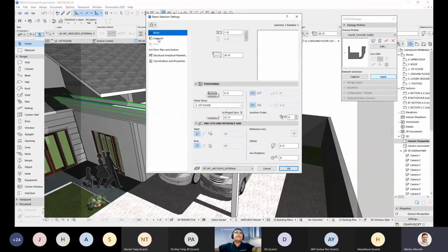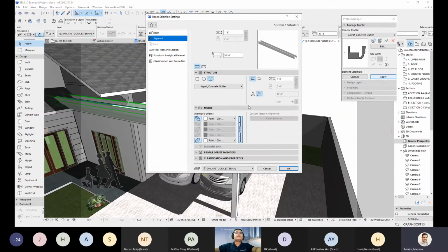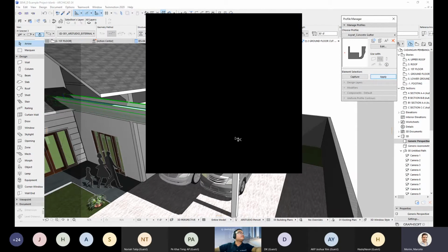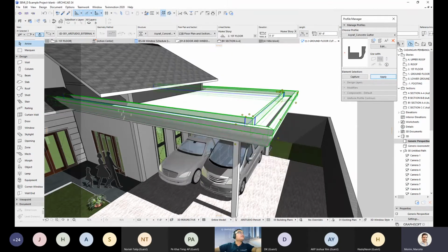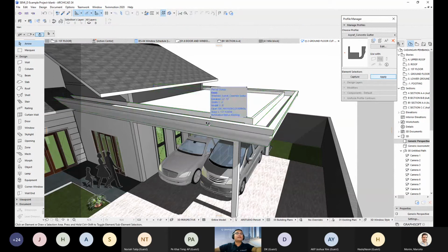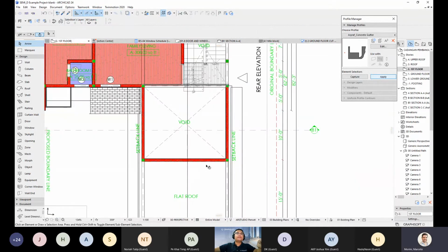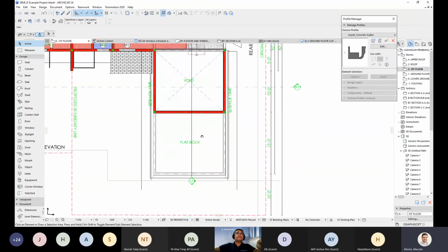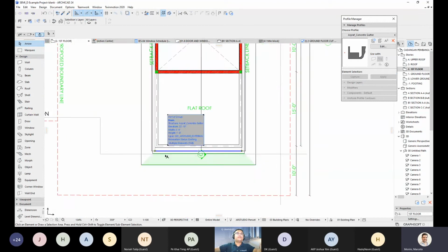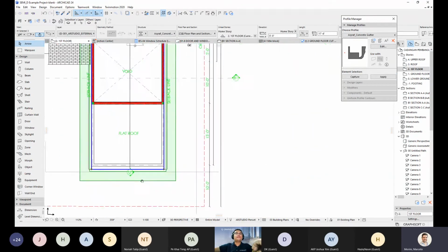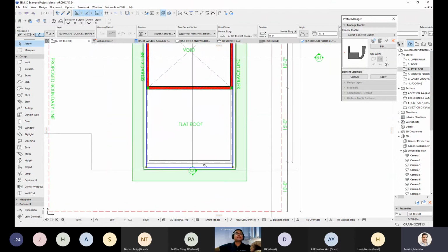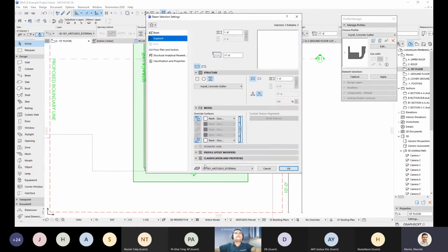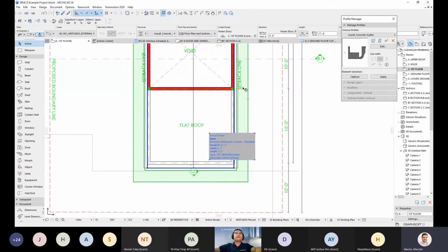Meanwhile, Ashraf, we have another question from Hajar. She is asking how you can show how the porch gutter would look in a floor plan, because sometimes unnecessary lines appear. We can control that by using the kind of visualization we want, whether just a symbolic visualization, or the actual representation of the element.